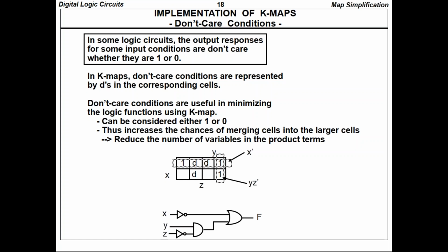Reducing power consumption is the major concern of any design after timing criteria. For that we use state machine reduction techniques and encoding techniques. Then one more form of power reduction is considering the don't care condition instead of either zeros or ones for initializing purposes. That's why I am saying this.